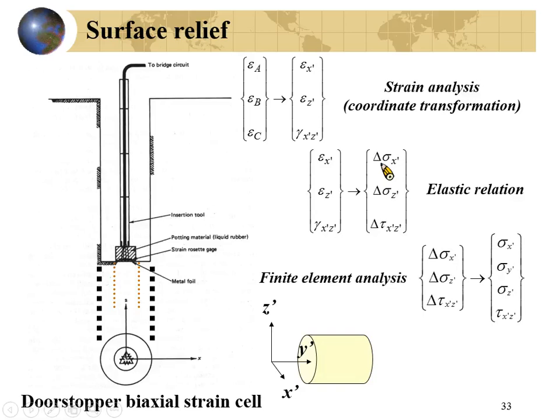And the released stress here is related to the in situ stress around here. Understand? They will have some relation. This relation is derived from the finite element analysis. It will be a little bit compressed. So you measure this, you will have this, and you can derive the stress difference from the elastic relation, and from the finite element analysis, you can derive the stress state at this point.